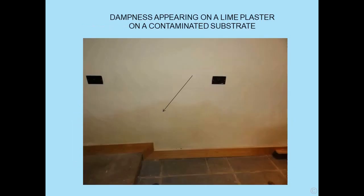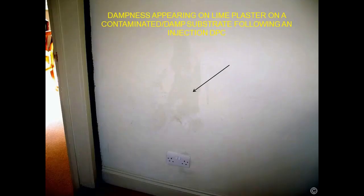Just a couple of examples: dampness appearing on a lime-based plastered wall, contaminated substrate, you can see the dampness has caused the spoiling. And similarly here, it was used after an injection process on a historic building. Don't use lime-based materials. Unfortunately, excellent for most uses, but not good where there is any form of dampness or salt contamination that's likely to be persistent.